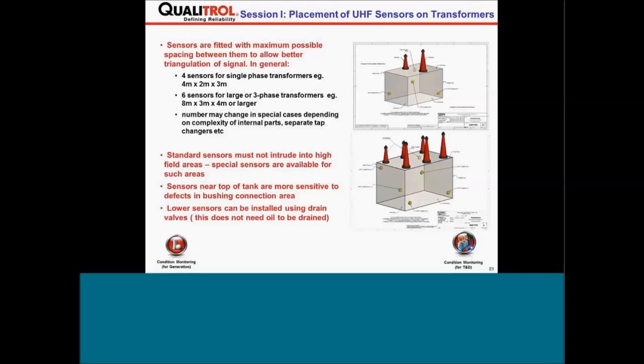The top right hand drawing shows the positions of these couplers. Basically they're in a diagonal formation on opposite walls of a transformer, with the diagonal swapped over from one wall to the other wall. So they're basically not all in the same plane. You're trying to create a very spatial spacing and positioning of the couplers.